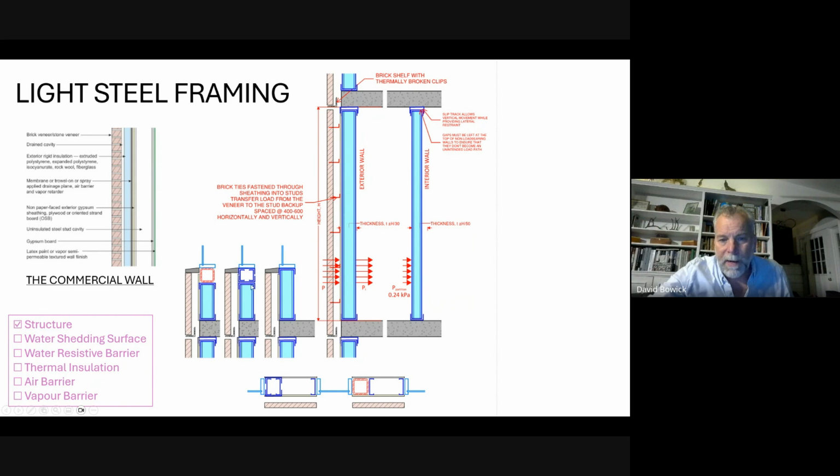In that case, we might put a box beam at our window sill. And the window head detail would be similar to the sill detail. I only drew the window sill detail, but they're quite similar. So we do a box beam. We take two studs like this, two tracks like that, and we make ourselves a box. And we screw that to the top of our knee wall. And that becomes the element that spans horizontally over the width of the window.